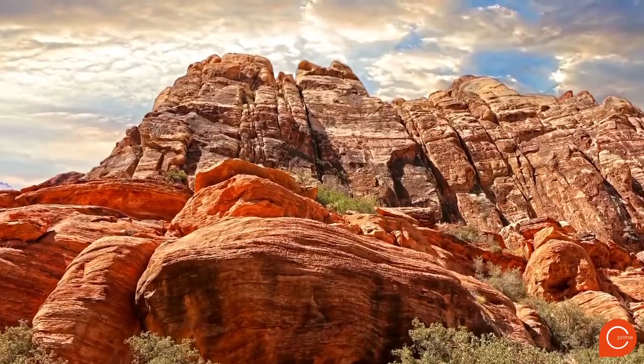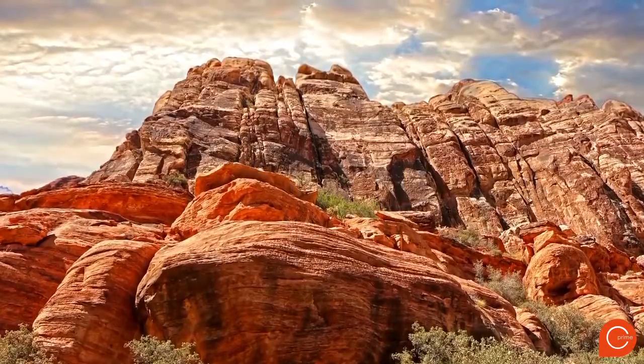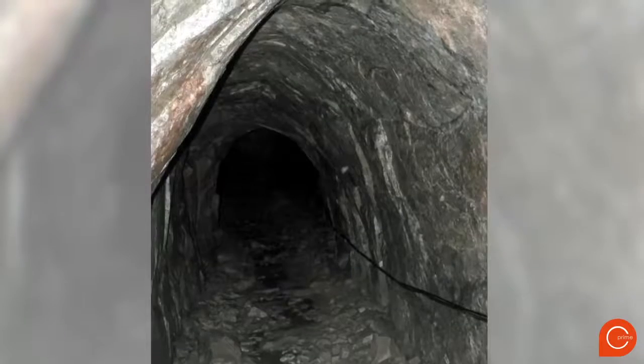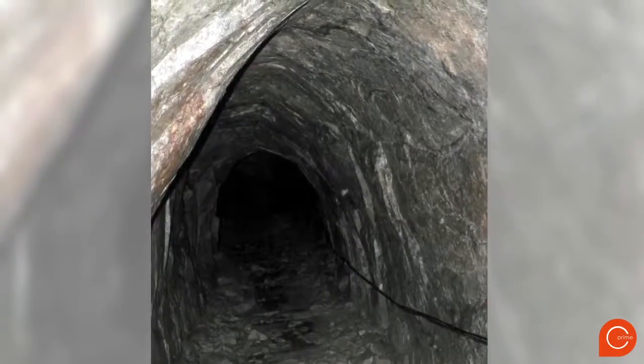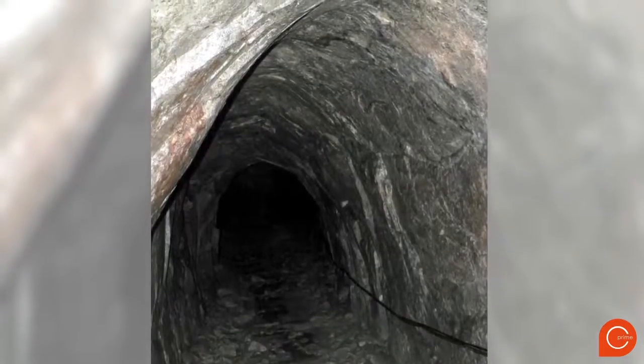Rock, on the other hand, behaves a little bit differently in that it does have some tensile strength. You could make a rope from it. Not that it would be very useful, but it's a good way to imagine the difference between soil and rock mechanics. In fact, rock generally has more strength than soil for all types of stress. This additional strength gives rock the ability to transfer forces around a tunnel just like the lining discussed before.